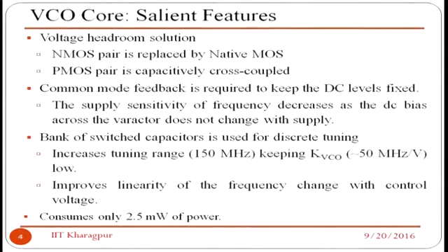Like KVCO here, there is another term, KVDD. KVDD means the change of frequency with respect to the change in the bias voltage, that is delta F over delta VDD. So the common mode technique utilized here can also help make this design more robust against fluctuation of the bias voltage.